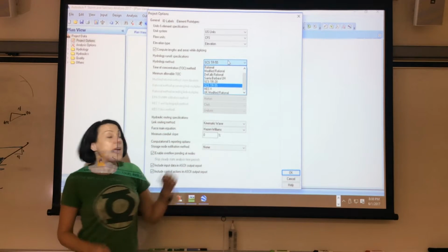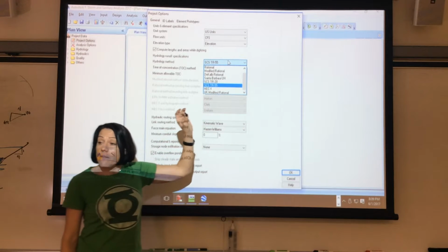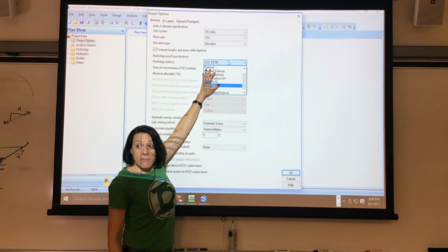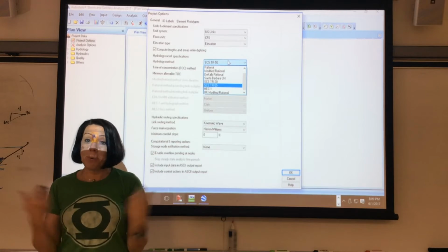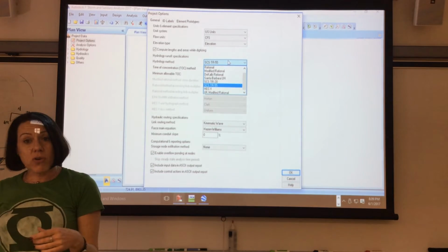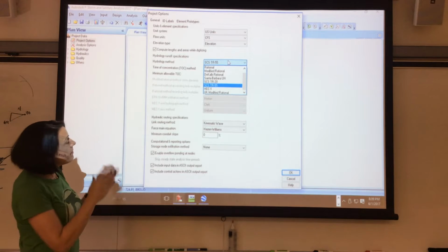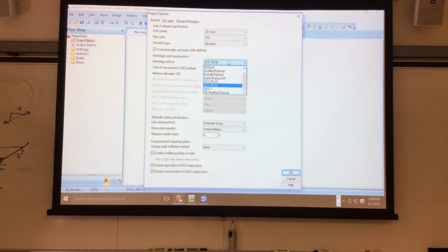Modified rational. The rational equation is for storm pipes. They decided to modify that for storm pipes because it's in CFS, and there's no hydrograph for the rational. For the modified rational, they actually put it into a basically triangular shaped hydrograph where the peak is where the time of concentration is at. Okay, so we're going to just continue with the TR55 for right now. HEC-1 is now HMS.